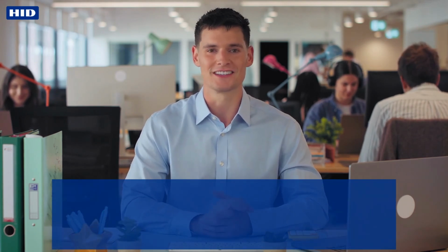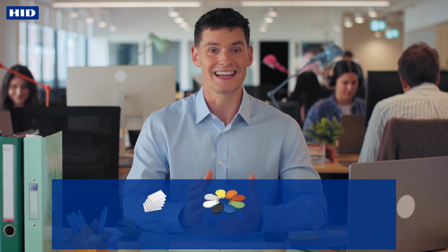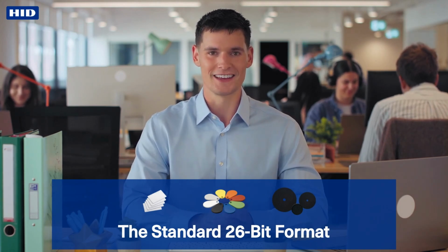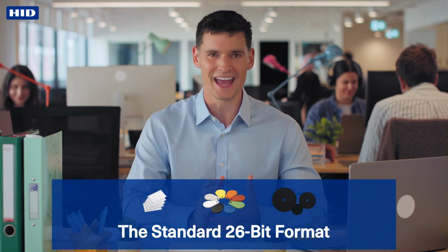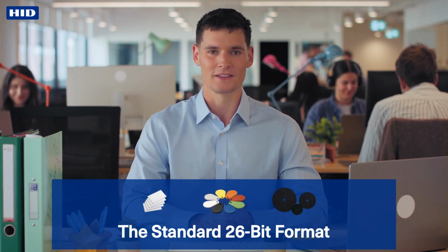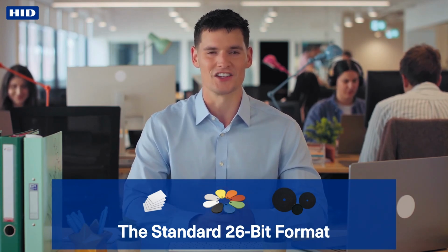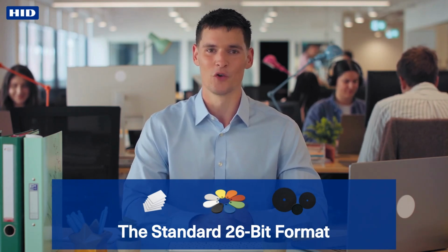The format in which a card is programmed is determined by the data pattern that will be compatible with the access control panel. All HID credentials, cards, fobs, tags, etc. can be programmed with the standard 26-bit card data format. The standard 26-bit format is an open format. An open format means that anyone can buy HID cards in a specific format, and that specific format description is publicly available. The 26-bit format is a widely used industry standard and is available to all HID customers. Almost all access control systems accept the standard 26-bit format.